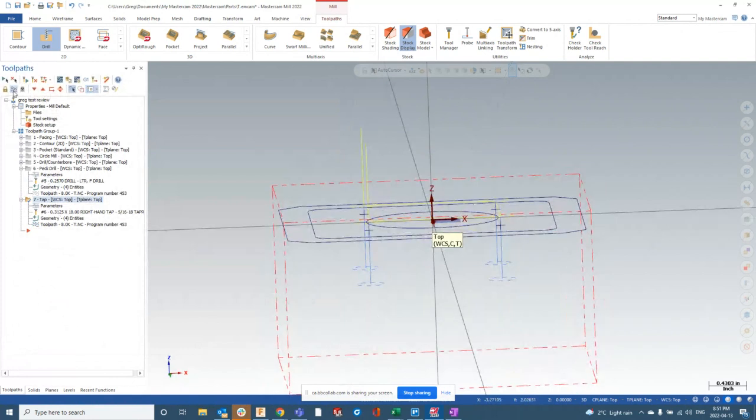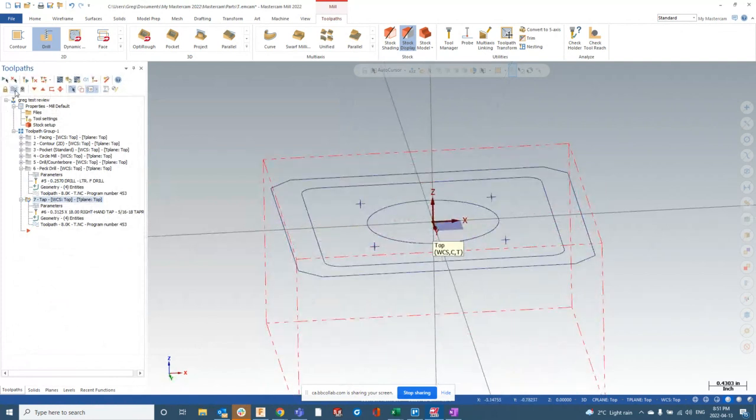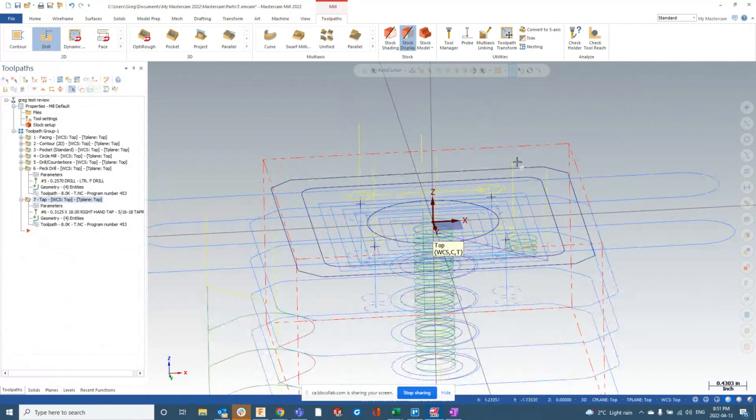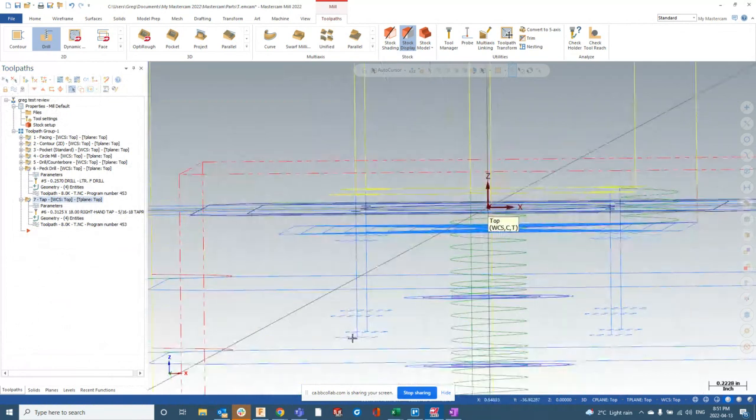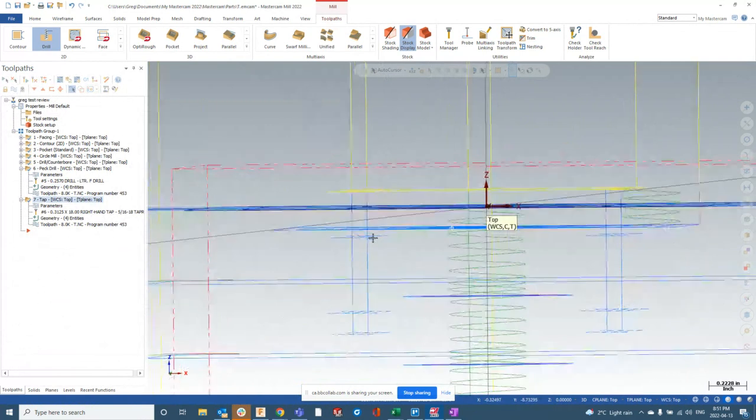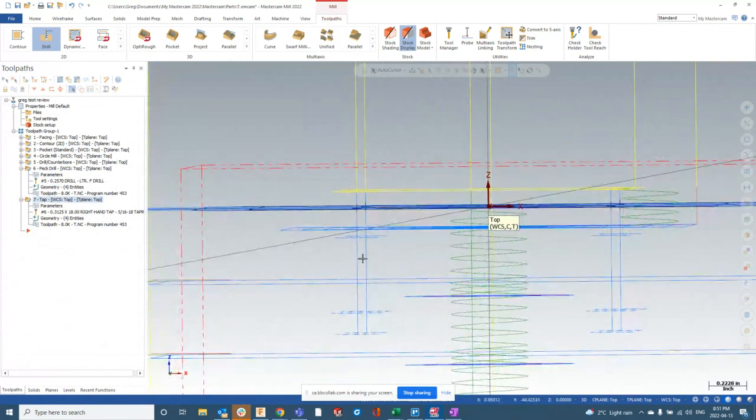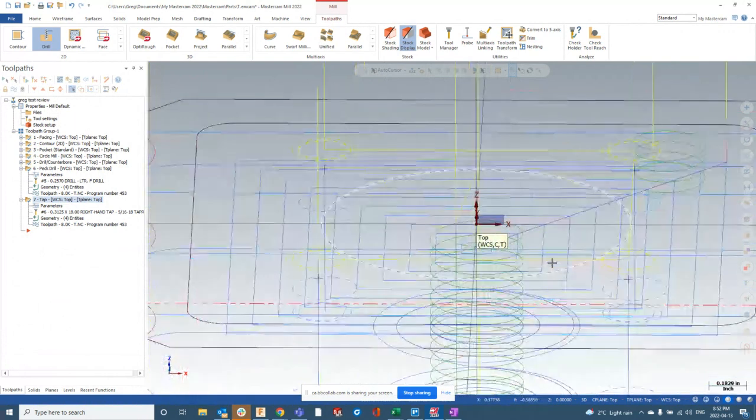Now, if I grab them all, you'll notice that my drill goes up to here, and my tap goes up to here. So we get the ½ inch of threads, and that ½ inch of threads is from here to here, right? And then this extra is just us drilling a little bit further to make sure this tap does not crash into the bottom of the hole, okay?